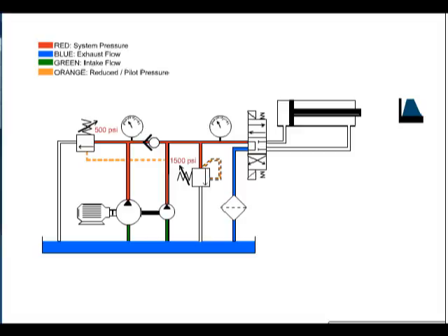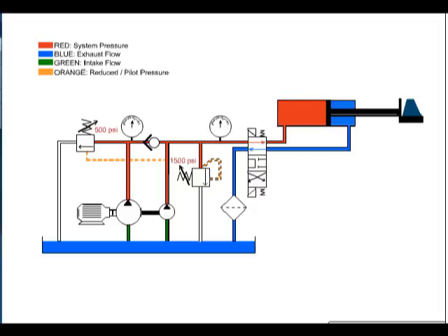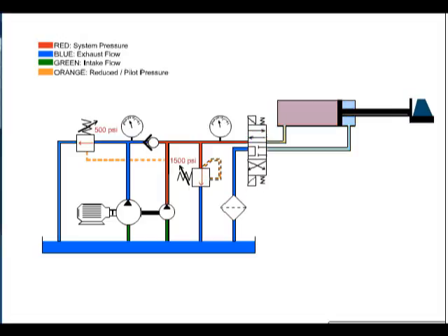If the pressure requirement is below the unloading valve setting, both pumps work together to provide a rapid approach to the load. At this point, the system pressure increases, thereby opening the unloading valve. The flow from the high-volume pump is directed back to the tank at a minimal pressure. The low-volume pump continues to deliver flow for the higher pressure requirement of the work cycle.